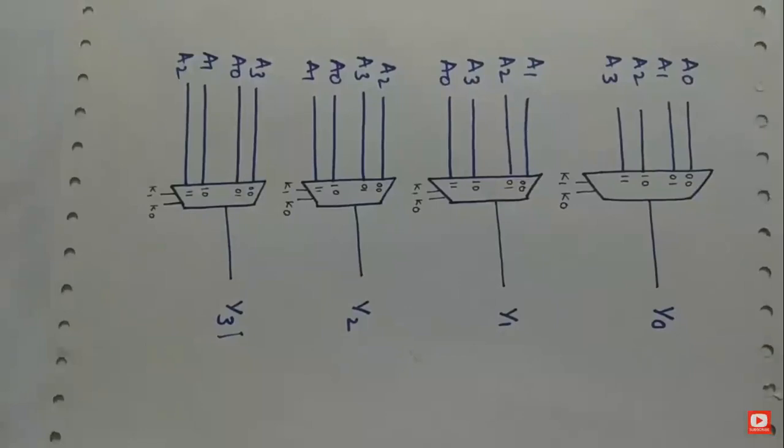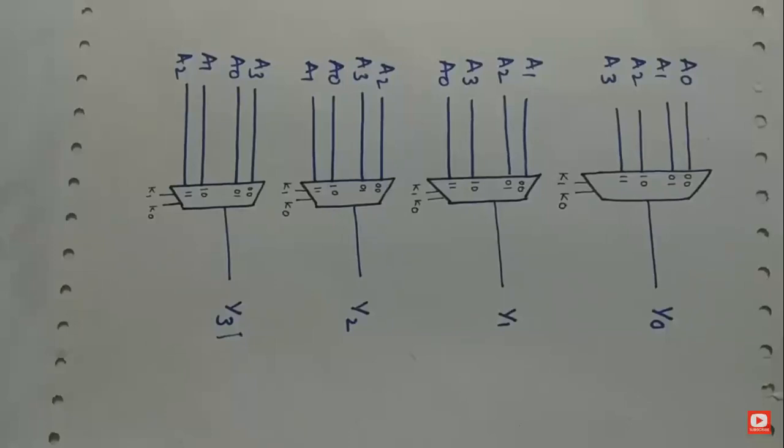As you can see, it looks better than 2:1 multiplexers, but you know that as we go on, if we keep on increasing the multiplexer size, it will be a problem. So mostly you must use 4:1 or 8:1, not more than that, otherwise it will be a problem. So you must learn how to design using 2:1 multiplexers for sure. So this is how it is done.